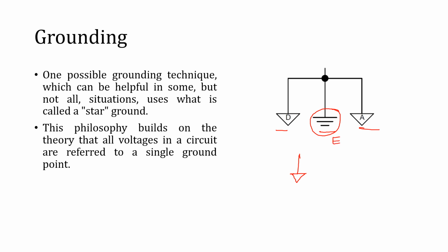When you have a symbol in the circuit like this, it means you have connected the ground with the main power supply, but it is not certain that the power supply is further connected to earth or not. When you are sure that it is connected with the earth supply, then you can use this symbol to show that our circuit is properly earth grounded. So that is the philosophy behind three types of grounds: analog ground, digital ground, and absolute ground or earth ground.